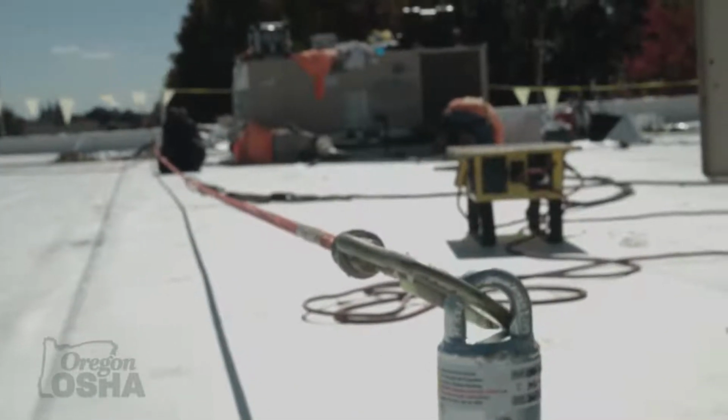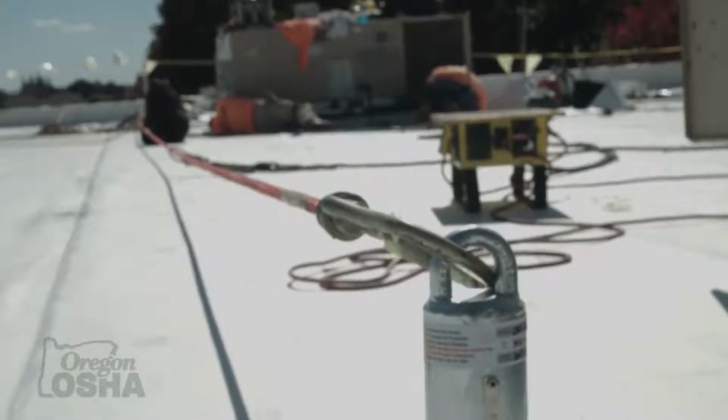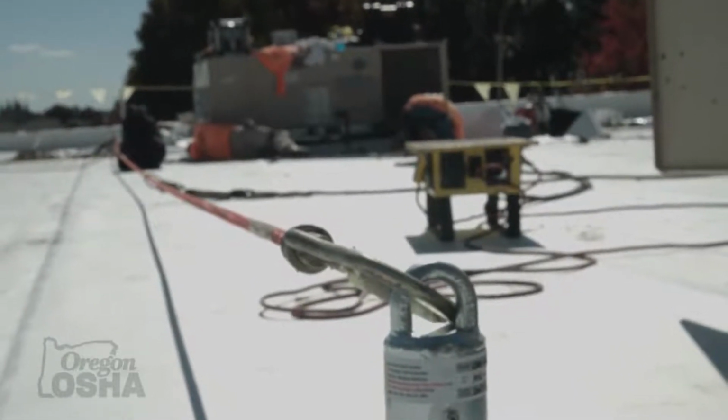It could mean an engineer, a structural engineer or a mechanical engineer who has been able to self-engineer horizontal lifelines or is able to look at the loads going into a concrete column or a wall or a form and say that yes, the way that this is situated, it can handle whatever the loads are that are going to be put into this, along with whatever else it had to support prior to that. Horizontal lifelines are probably where we see the qualified person in fall protection being referenced the most, because all horizontal lifelines have to be designed, engineered, and used under the supervision of a qualified person.